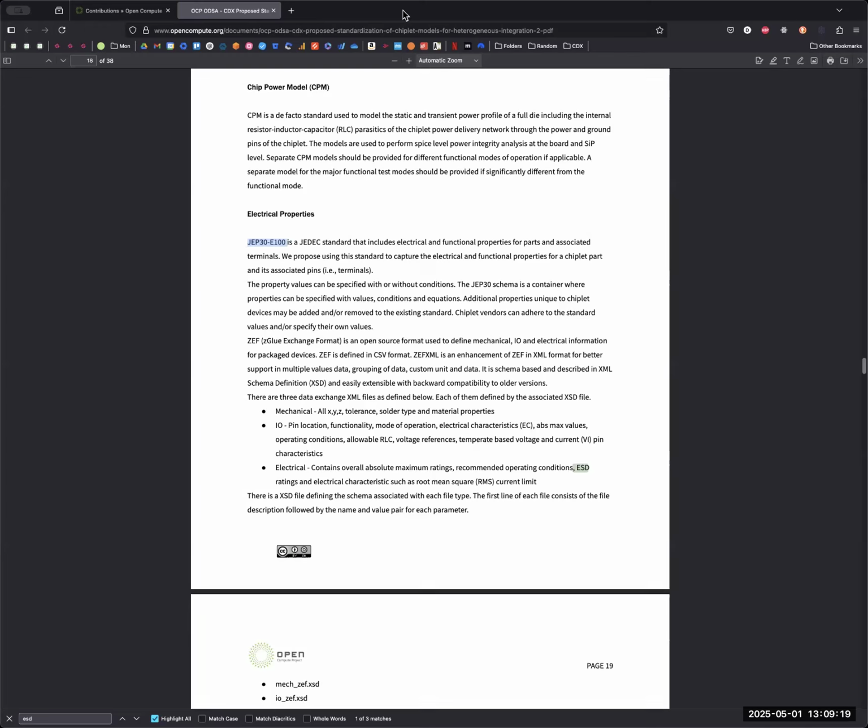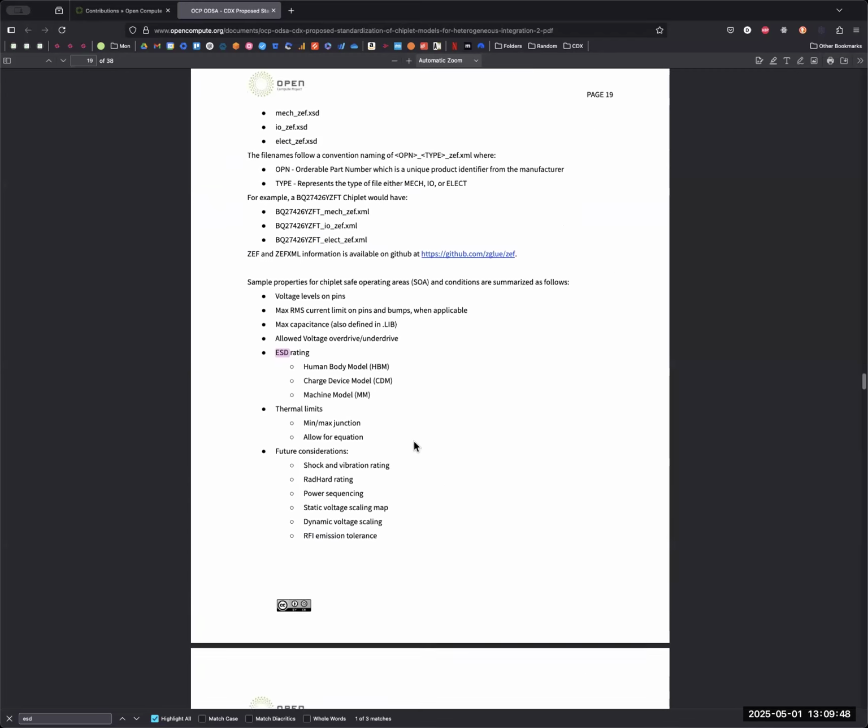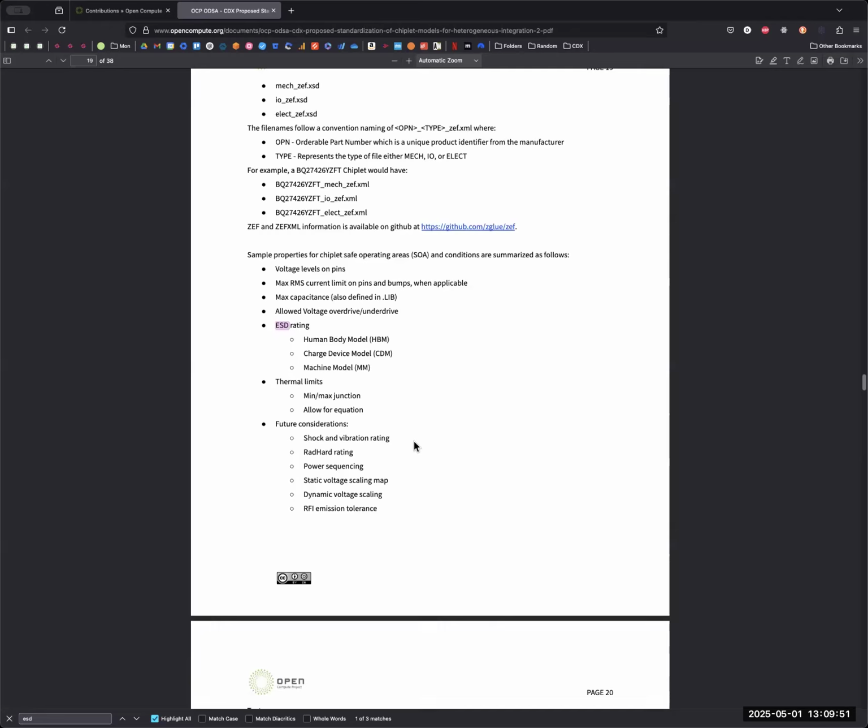Now, once you go to interposers and things like that, there's basically two sides to this. One is some of the micro bumps are going to go out on the bottom of the interposer and go to the outside world. That outside world will have the ESD requirements, right? It may be charged and so on. Then you have the die to die, where people are saying you are not going to have a human body model, right? But you may have a charged device model, CDM, because you are assembling in the assembly environment. You may have charging of the device.